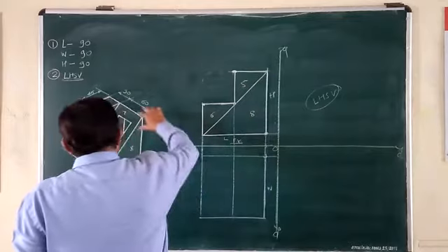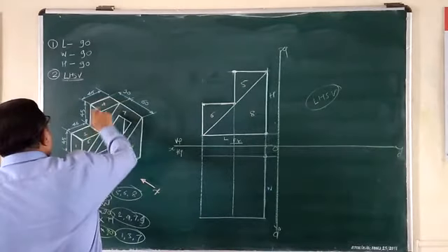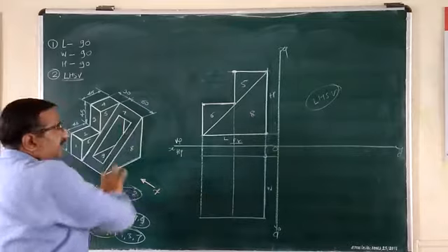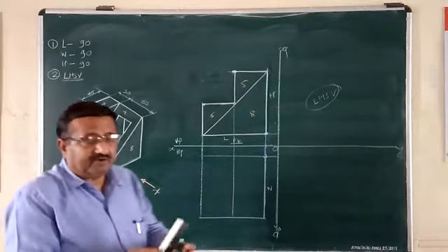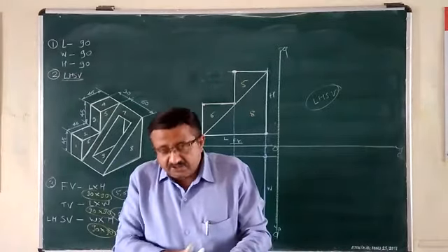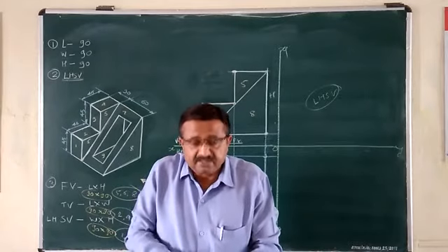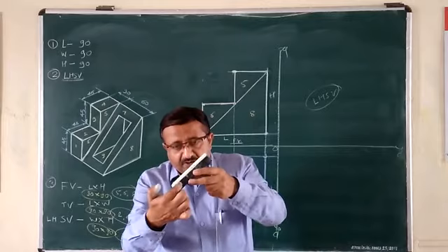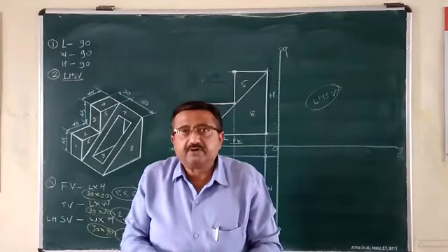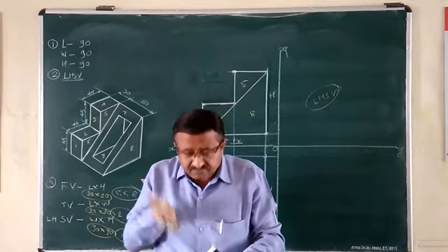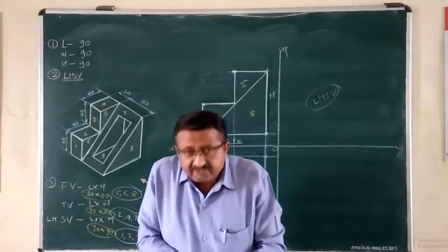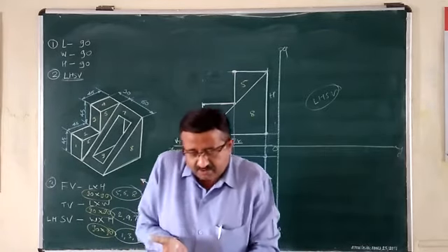Okay, so accordingly now this surface is here, 2, 4 and 7 we have to mark. Though this surface of this duster is slant, when I observe from top, just see, what will happen? Its length will be compressed. It will reflect its apparent image, its horizontal size. This slantness appears in front only, but when you observe from top, this slantness will not appear to the observer. Only the compressed length will appear and this entire surface will be present as it is.